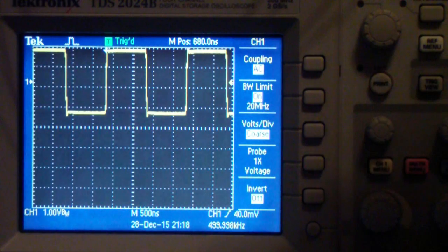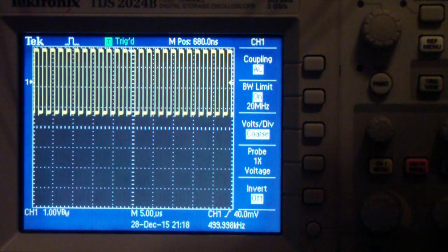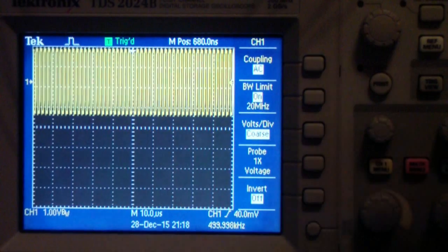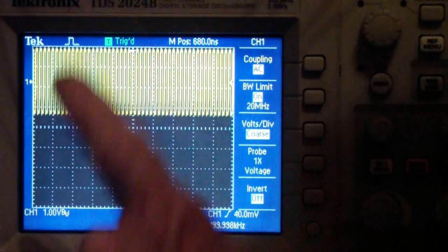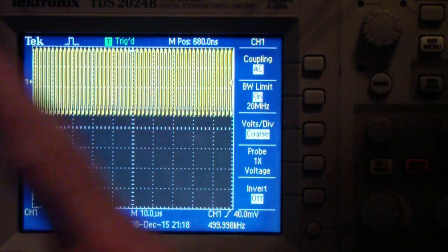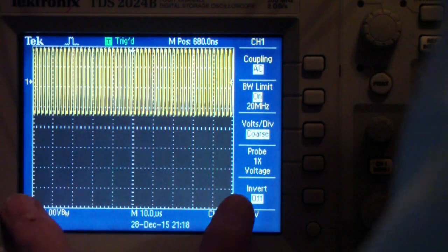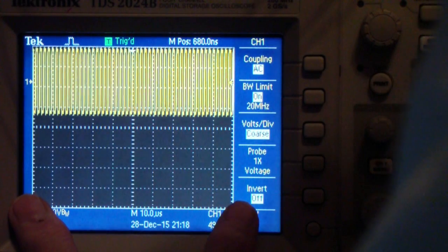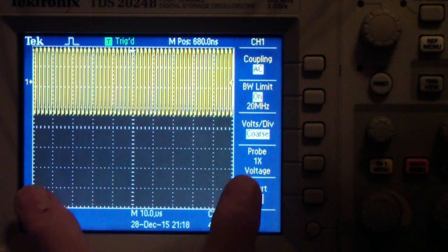On the other hand, if you give it quite a few cycles to work with, like that, your resolution will be better, but as you will notice, and if you watched Alan's video, he talks about this quite a bit, your total span, that is the range over which you can see frequencies, gets smaller.